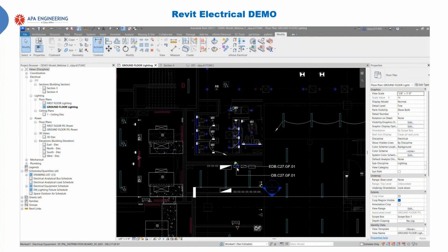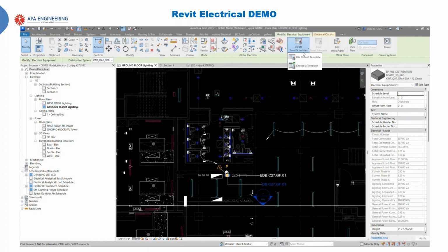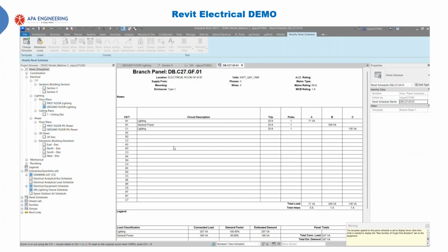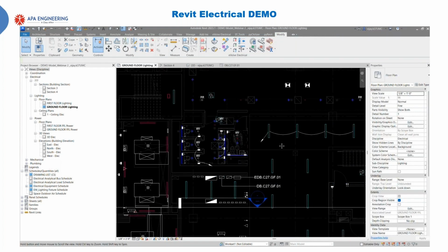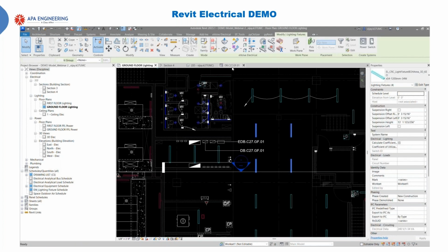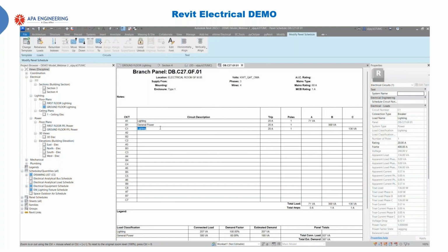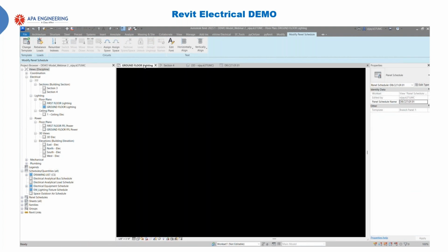And I can create a new DB panel schedule. Above you can see the system default template panel schedule. Now we created a total of 3 circuits, A1, B1, C1. In A1 we have created lighting, it's 20 ampere, and we can see that it's completely selected. We'll see one more example. We have these 4 lights here. Now we have 3 allotted. One is spare, A2 is a spare.